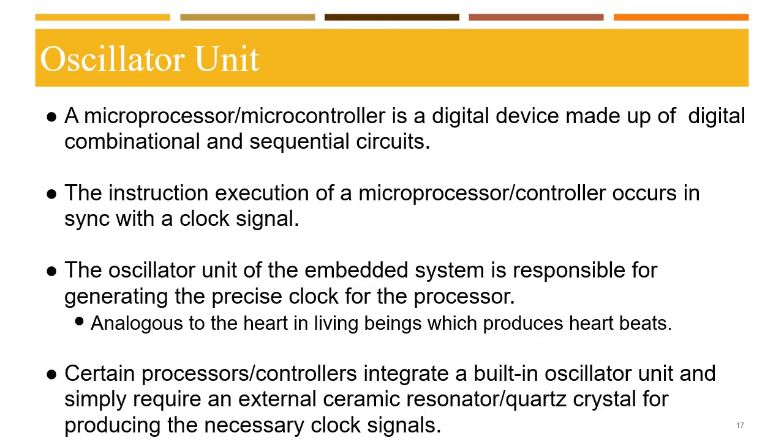The oscillator unit of an embedded system is responsible for generating these precise clock signals. It is the same as the heart in living beings, which produces heartbeats. Certain processors or controllers integrate a built-in oscillator unit and simply require an external ceramic resonator or quartz crystal for producing the necessary clock signals.